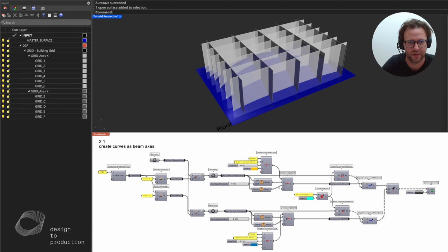And that's basically it. So from here on, the procedure is exactly the same, which we already experienced in the first model with the context and the grid. We create new component types. In that case, it's an L beam, so a longitudinal beam, and a T beam, which stands for transversal beam. And we fill these components with information. In that case, with the reference axis, which is exactly the intersection curve of what we have seen here, what we set up in the beginning.